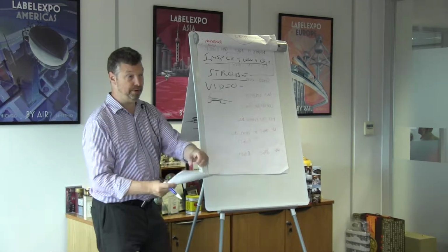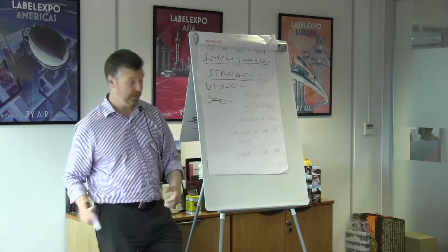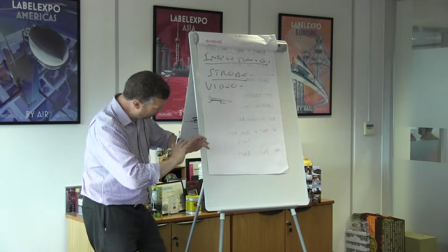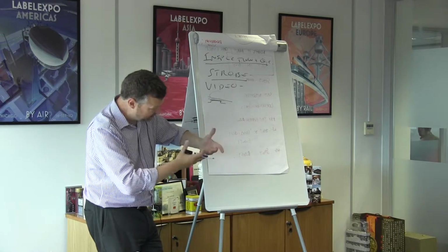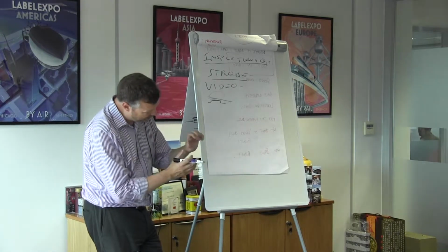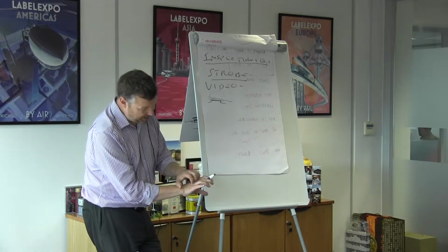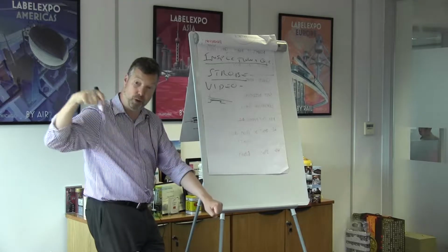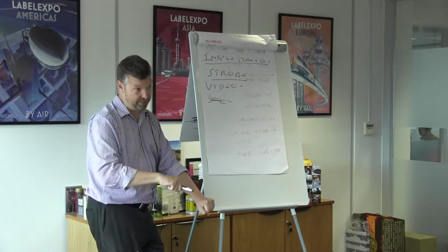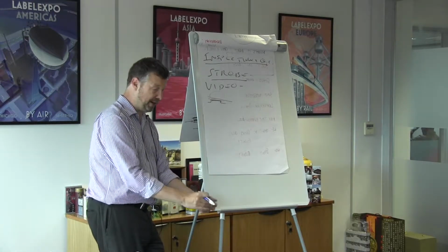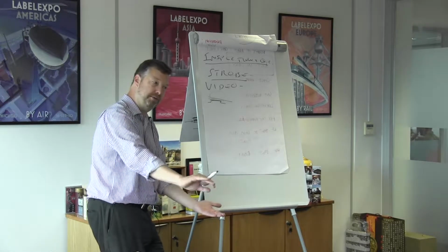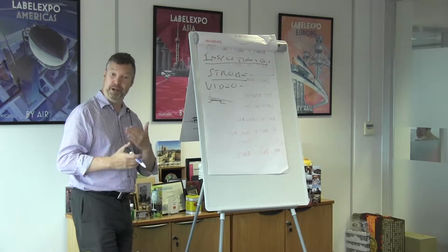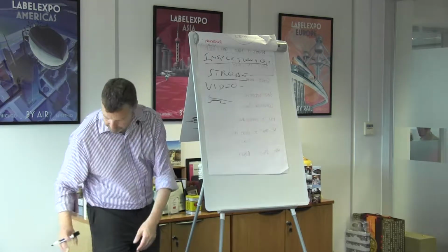And the other thing that the rewinder operator is looking for is if the matrix has been properly stripped. So if you think about when you die cut, you have like your cookie cutter going over the web, the shape of the label you want to cut out. It's cutting out that label shape, and then it's pulling away the waste, the matrix waste, and winding that away. But if that breaks for any reason, and the matrix is still on there, then that label won't come off when you try and put it onto a container. So it's another thing that the rewinder operator is looking out for.